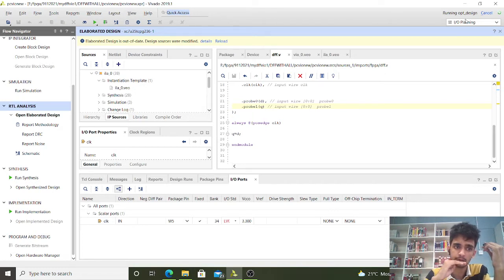If we didn't apply this clock wizard, we are not going to see any clock signal, because, as you know, sampling a signal with itself becomes zero or constant. The clock is sampled with itself, so no clock will be visible on this ILA. So then we have to introduce the clock wizard.